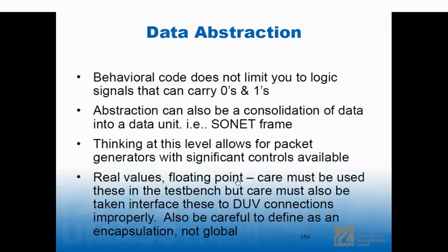So real values, floating point, MATLAB is your friend in signal processing systems, except MATLAB doesn't know anything about digital. So when it gives you a file, remember that sine wave I talked about in the middle, where did that come from? Well, it probably came from MATLAB, right? And the noise probably came from MATLAB. Well, it's probably some fixed point thing, not 32 bits or 16 bits or 12 bits or whatever your signal processing chain is. So be careful with that stuff. And you might even just need to test it, right? Test without your DUT in there, see that the signal coming in gets treated properly by your detectors.